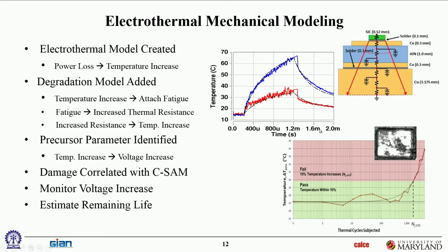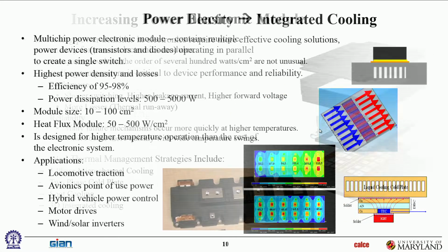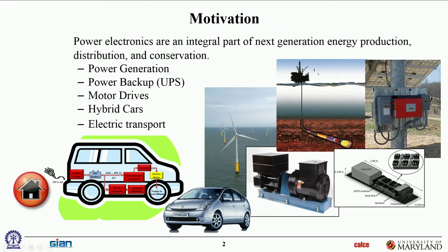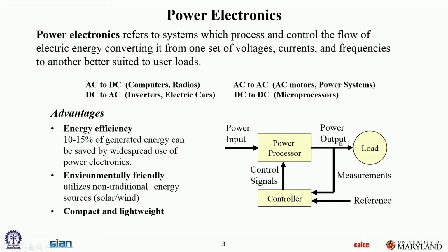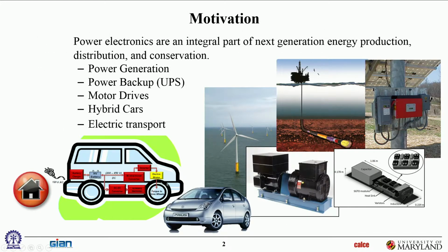And some of these power electronics are in very harsh environments, as I mentioned. These are in exposed environments, very high temperatures, so trying to manage junction temperatures there is not a trivial challenge. Same thing with automotive. Some of the automotive electronics is in pretty harsh conditions.